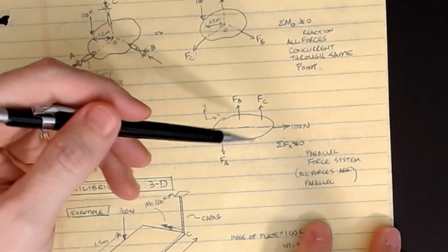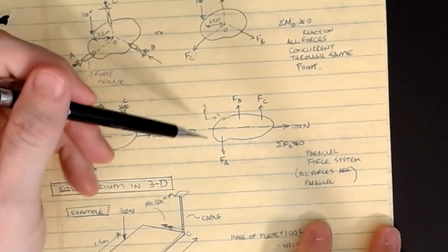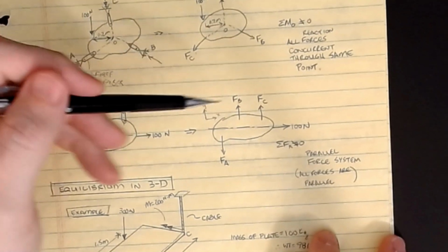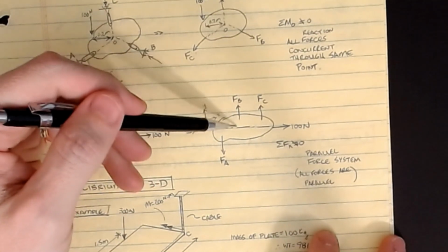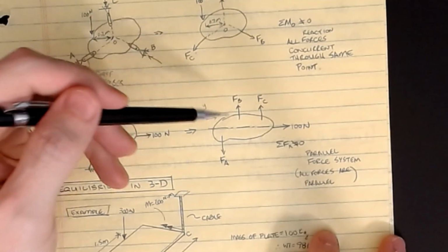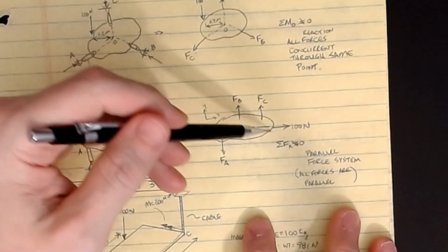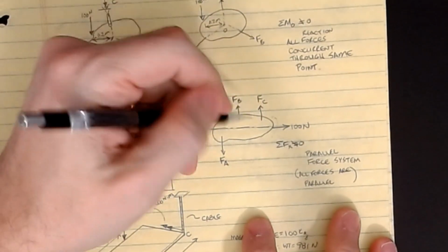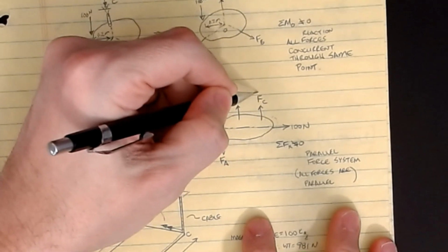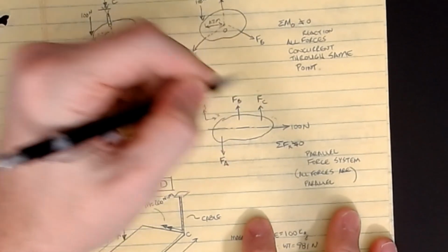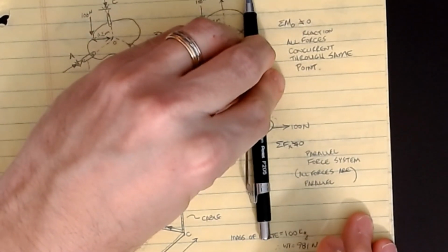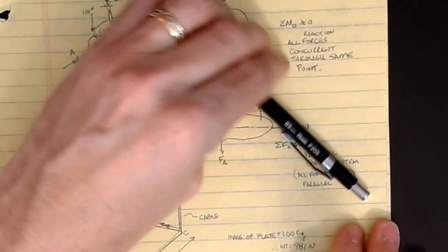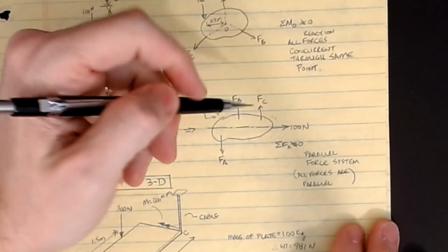If we now start to think about this, in statics we assumed everything was rigid and there was no deformation allowed. But when we get to mechanics of materials, what you'll find out is that this object will deform, and it doesn't take much to put something back into equilibrium. All we have to do is apply this, and if this thing moves over a little bit, say to like that, this force would also move over, and now if it's linked up here, we've inclined that linkage just a little bit. If I exaggerate it, when I pull this bar over and let it deflect, it is now oriented that way. When it deflects like that, it's got an X component associated with it, and that would be the same for all of these.